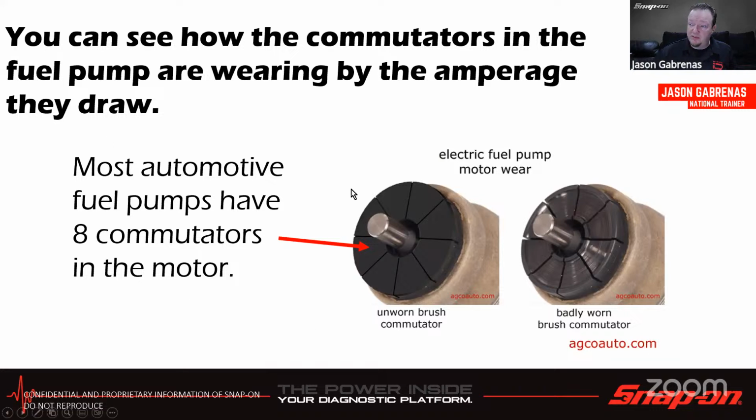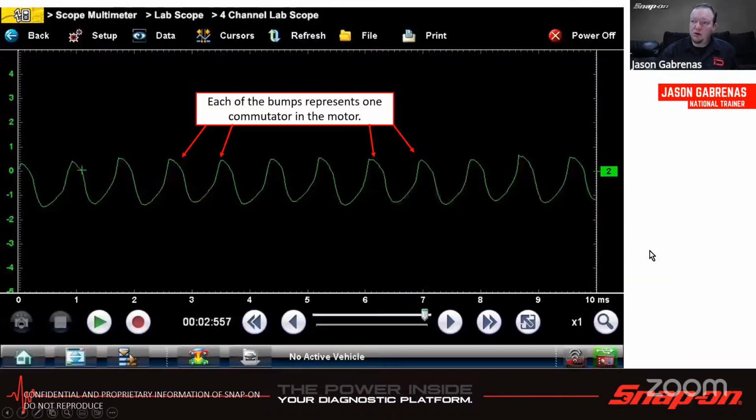Now, most automotive fuel pumps that are brushed have 8 commutator segments in the motor. And there's an example of a badly worn one over there. Each of those bumps you're going to see on the scope screen represents one of those commutator segments going by in the motor. So we can see they're going up and down and up and down. As it spins by, the current goes up and then the current decreases as they go past.